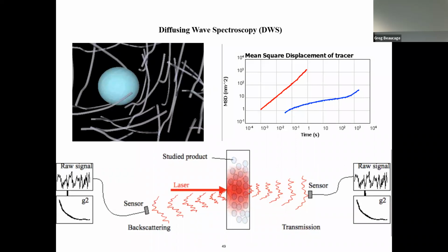They can have viscous or Brownian motion, where the mean square displacement is linearly proportional to time. So you can see it goes 1 decade, 1 decade. Right, so it's power 1. Or you can see elastic motion where the curve plateaus out. If it's elastic, this is just a fixed mean square displacement with time. Time doesn't matter. It's a solid.